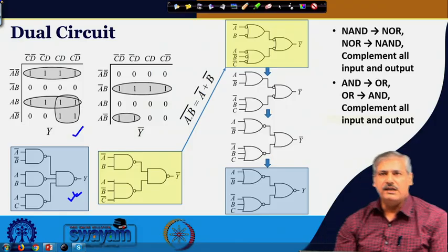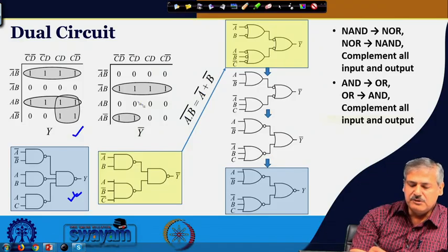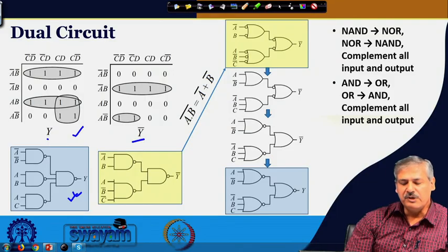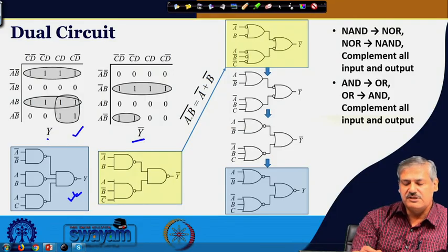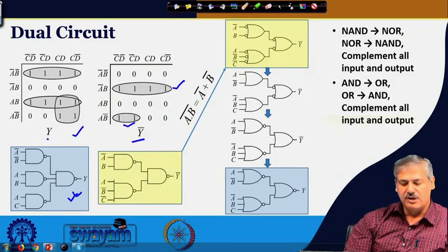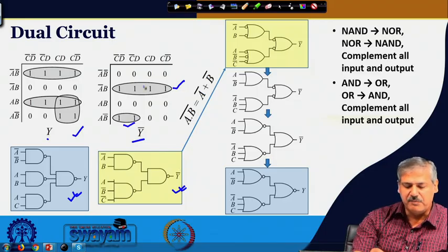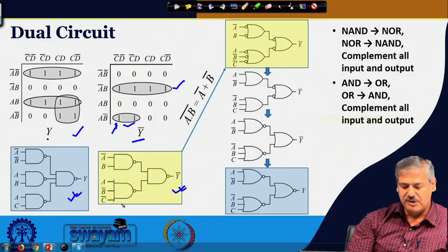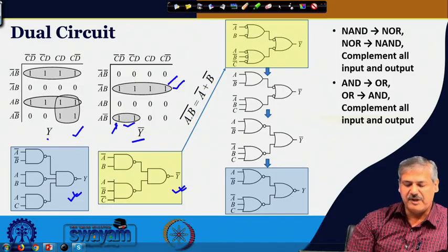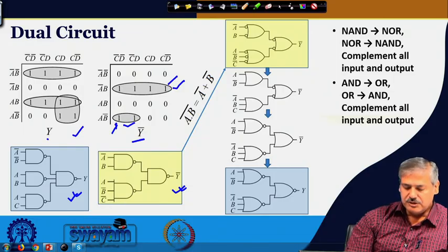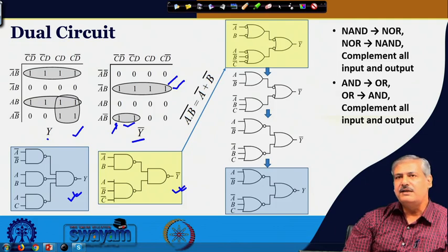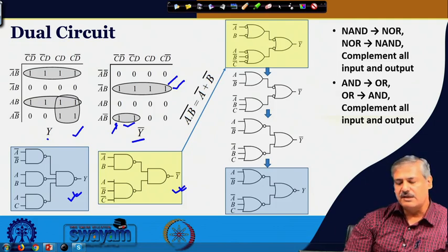Another way of looking at it is, this was y, you consider y prime. Okay. So, y prime is what? Its inversion. Wherever there was 0, there will be 1. So, these are the cases. The corresponding circuit that you get over here by considering these two groups A prime B and A prime B C prime, is it not? This is A prime B C prime, and this is your A prime B. From that you get the corresponding NAND circuit instead of the AND OR circuit.